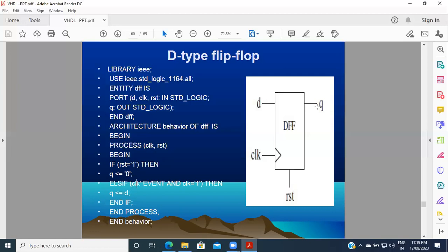There are two types of signal attributes in VHDL: those that return values and those that return signals. The 'event attribute returns a value, so clock'event returns a value, not a signal.